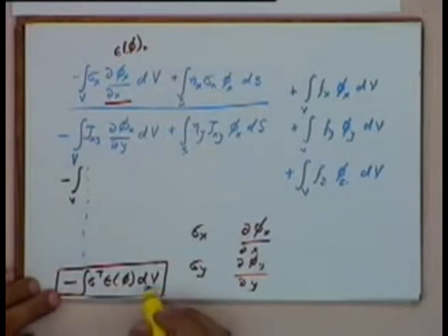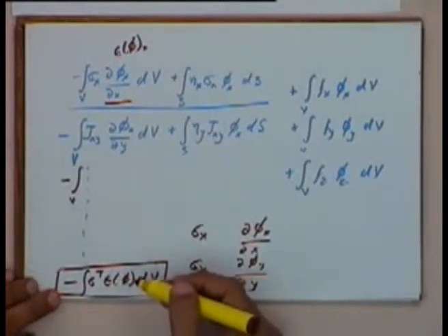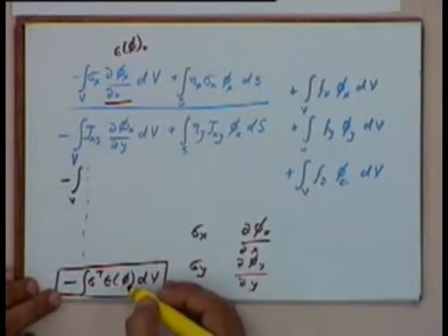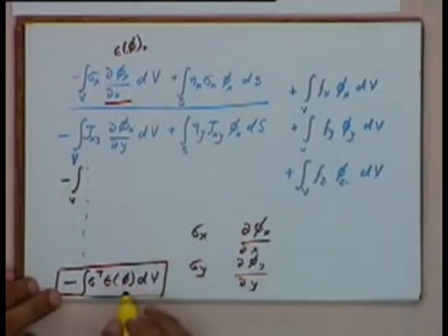Okay, and as I said, this phi is possibly a displacement field that we are giving to the object. If you are familiar with the principle of virtual work, this phi is actually the virtual displacement that we are giving to the body. What we were calling weights earlier is actually a virtual displacement that we are giving to the body. If you give it a virtual displacement, then the strain due to that virtual displacement is the strain epsilon phi.